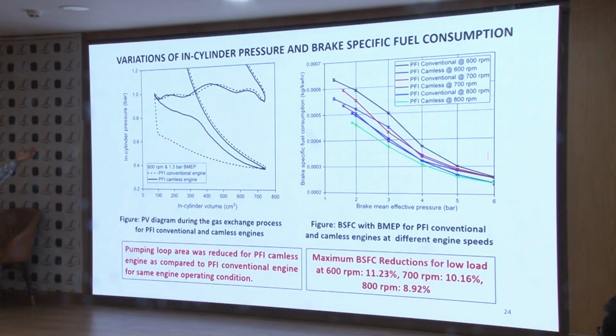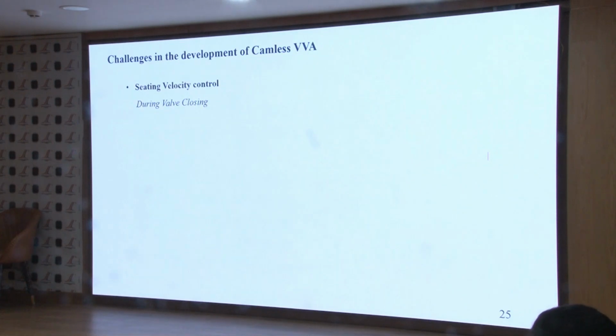Since there are some limitations with the solenoid valves, this technology has been tested only up to 1600 RPM. So this is our proof of concept. Now we are working on the next phase, where we can extend the RPM range with advanced solenoid based systems.